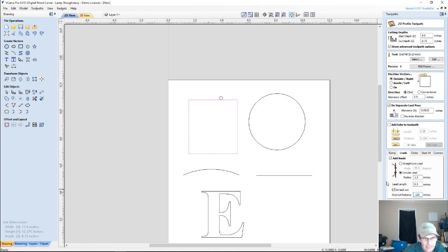It leads in into one area, comes around and does the profile cut, then comes past that beginning point and leads out away from it. You can set that. You don't necessarily have to, but hey, it's another added option. Now you're not coming in and out on the same point. And some of these things you should really do some test cuts just to see the differences between them and how everything reacts.